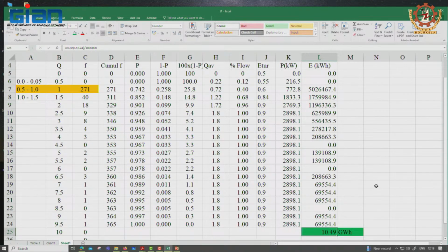Also, now we assume the transformer efficiency and generator efficiency to be flat from no load to full load. You can think about that; if there is a substantial difference, you can incorporate those curves into this rather than treating them as constant, thereby making your calculation more accurate.